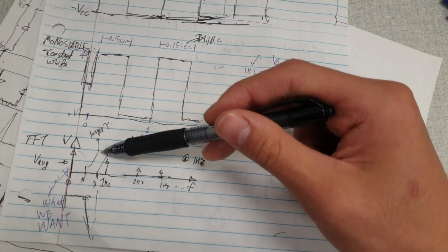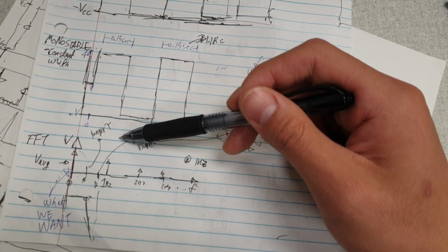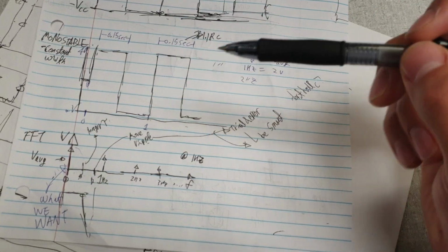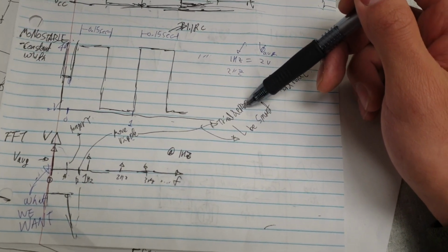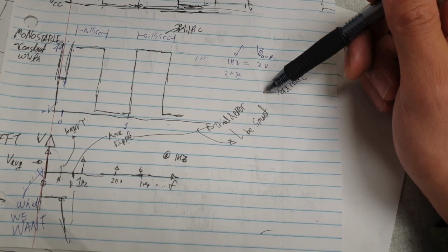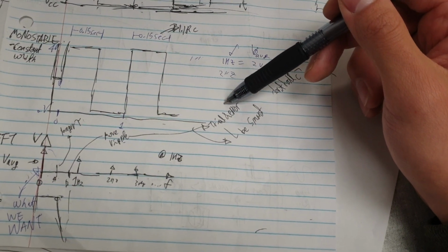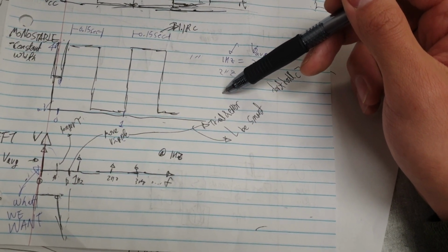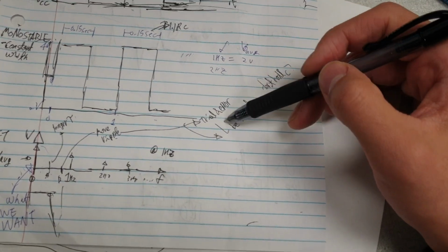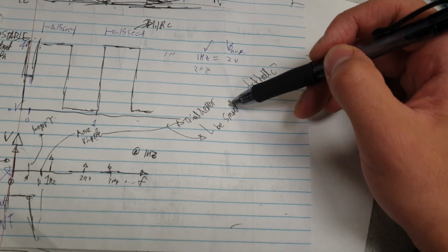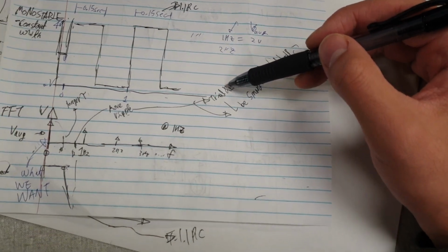And the time constant is just an RC. However, for the ripple, there's no given formula in determining the ripples if you go to like second, third, and fourth order. So we have to do a trial and error method to figure out the percentage of the ripple.